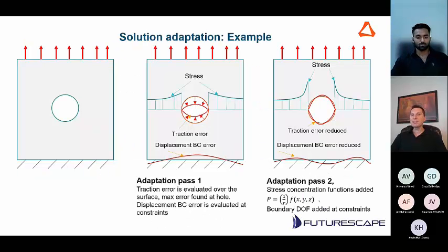Here's an example of what the technology of SimSolid is doing in the background. Here's an example of a hole, maybe it's a small hole in a part and whatnot. It might introduce some stress concentrations or risers. So it'll basically do an adaptive pass going through this hole to find out what type of error calculations there might be, and it will do an adjustment on the second pass to make sure that the error is reduced in that model.